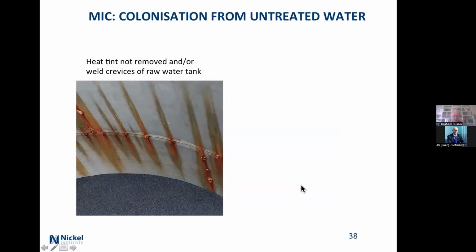This is different. Here's a potable water tank. It's used for storing raw water. And within about 3 months, you had the reputation, you want to have a shower, go and walk around the outside of that. Because the welding was a bit rough as guts, and there's a strong suspicion that the heat tint wasn't cleaned up properly around the welds. It's clearly been strip polished, but not very well. And so you've got all of this. And the reason it goes up and down, it's outside, it gets heated up. So the little chloride, the corrosion product comes out, the ions, they combine with oxygen, precipitate out. And if it's hot outside, then it goes up. If it's cold outside at night time, it goes down.